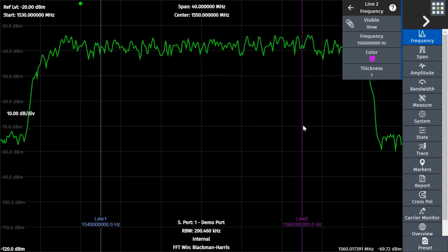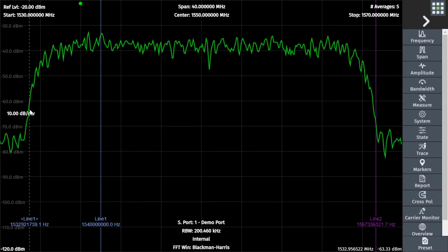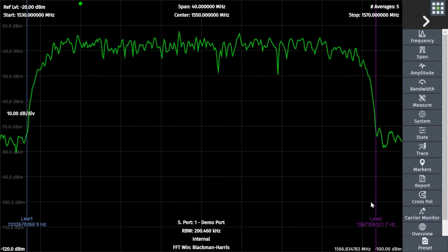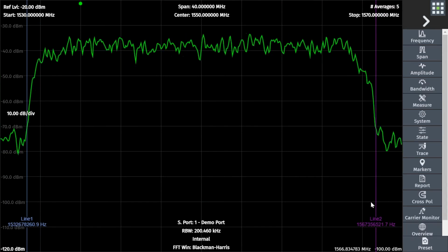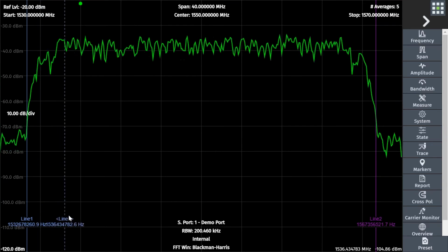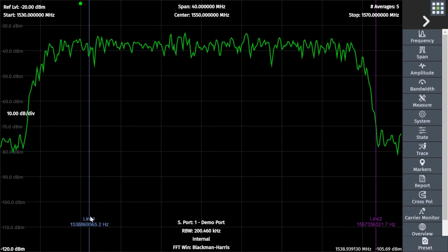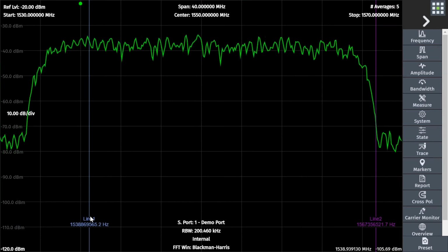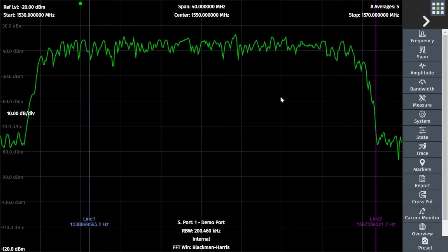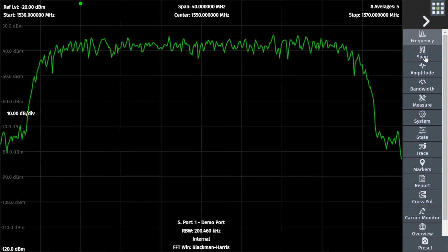And that's useful if you're trying to plot out the extents of the carrier frequency-wise. You can figure out roughly where the 3 dB bandwidth is in a manual way, or if there was a particular item of interest on the plot, like a particular interferer, you could align the line with that and generate some reports from that. We'll see later how you can dump out the contents and take a closer look at that. Okay, I'll just remove those lines with a quick preset.